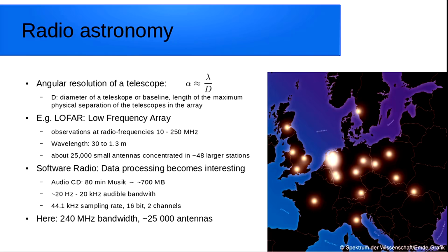So also, you need a really precise timestamp of each signal on each antenna, and then you can process the signal from the different antennas with different phase shifts, depending on which direction you want to receive the signals from. And yeah, you can get a really good antenna gain by using a lot of antennas.